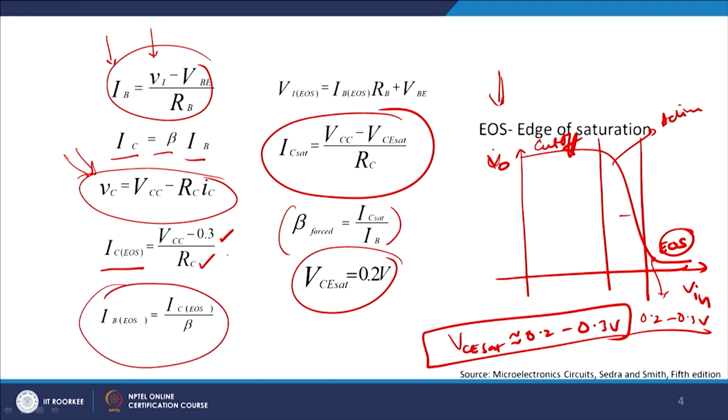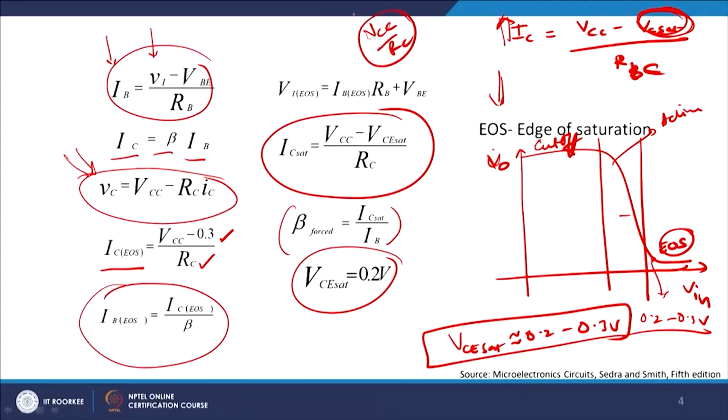So, that is very straightforward looking at it, but I wanted to make one important point clear here. Therefore, IC, if you remember, is nothing but VCC minus VCE(sat) divided by RC. Now, the obvious question is how can you maximize IC, because then you get large currents. You make this as close to 0 as possible. So, typically the maximum value of IC will be VCC by RC.